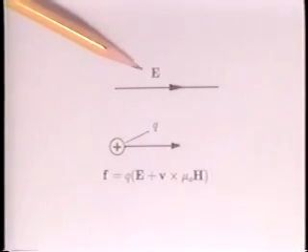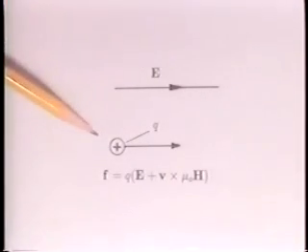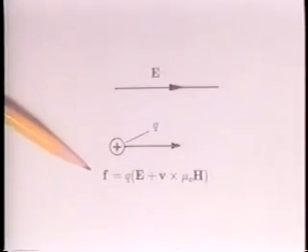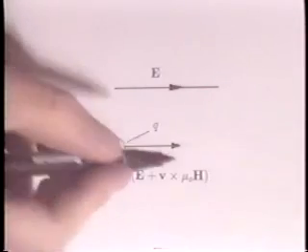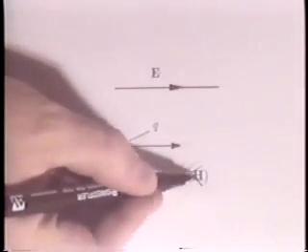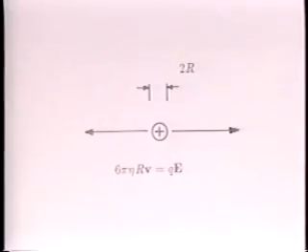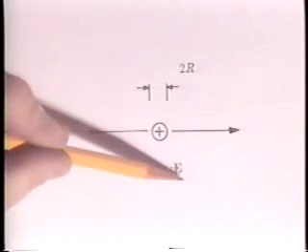In an electric field E, a particle having the charge Q is subject to the Lorentz force. For particles such as dust and smoke in air, their velocity is so low that even if there were much of an applied magnetic field, its contribution would be negligible. In air, the inertia of fine particles is often negligible. The electrical force is balanced by a drag force.